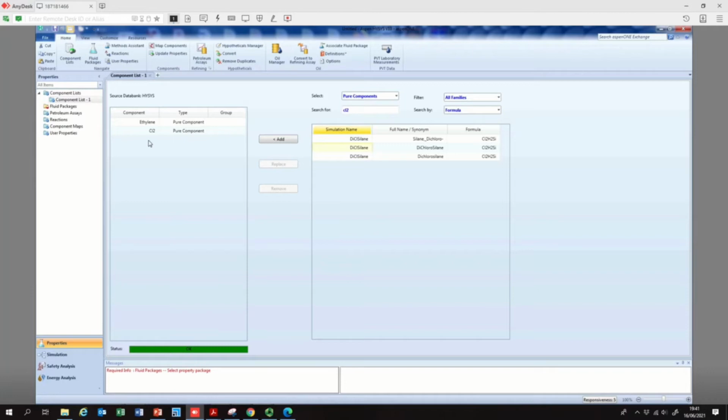Whatever we are seeing now is the procedure to use Aspen HYSYS. We open the software and then the first thing that we need to do is add the fluid components. If you have any process, or even just a small unit operation, say we are mixing A plus B in a CSTR, then we have to load component A and component B.